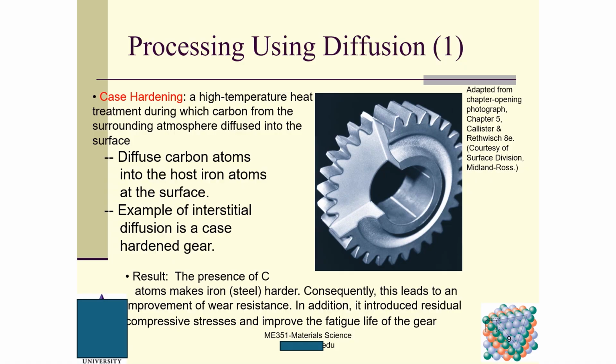Theoretically, you can provide carbon-containing solids in this chamber, but as I said, carbon-containing gases are most commonly used to case harden these specimens. So you have a chamber, carbon-containing materials, and your specimen, and then you elevate the temperature of the chamber, and hold everything at this temperature for a certain amount of time, and then you will get a case hardened specimen.